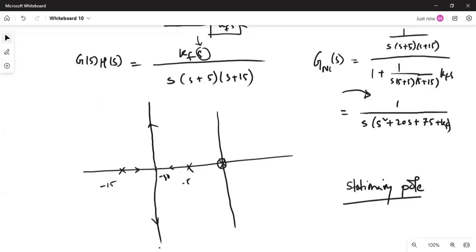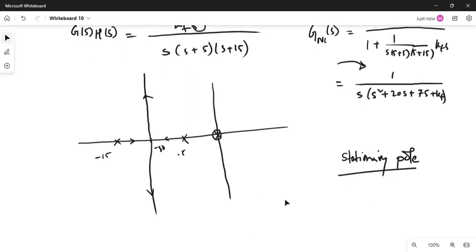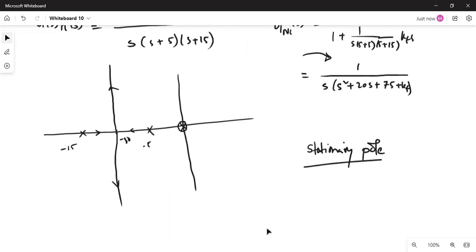What is next? We have to find the intersection of this root locus with your zeta line that is given. Your zeta line calculation is for the inner loop or minor loop. Zeta is 0.8.